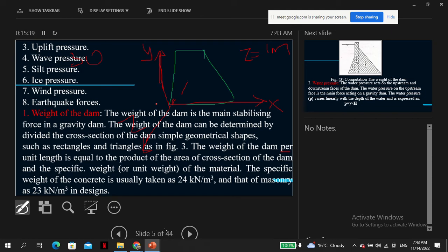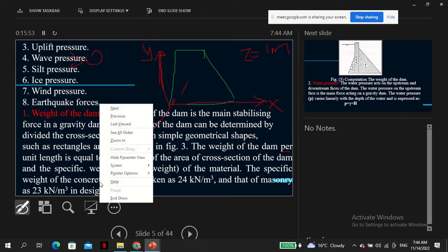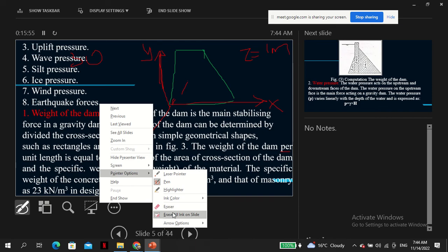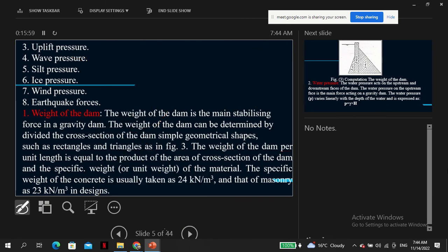If not, you have to divide into sections that are similar, and then you multiply and add eventually to get the entire thing. Of course, for simplicity in these designs, we shall assume that the entire dam is homogeneous over the entire length. So just design per meter, and then you can multiply by the entire length of the dam.